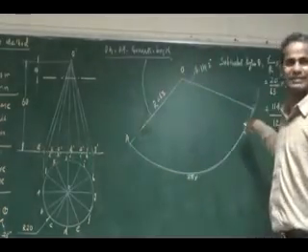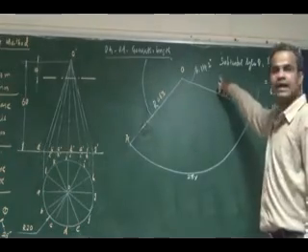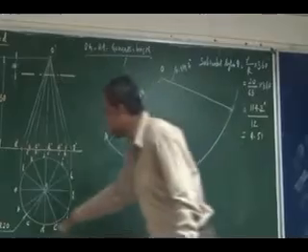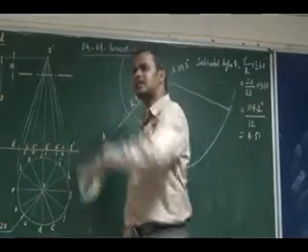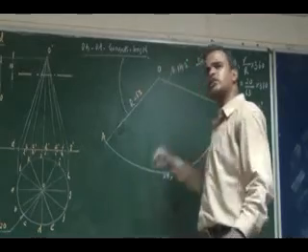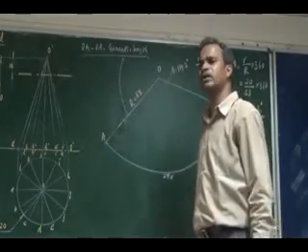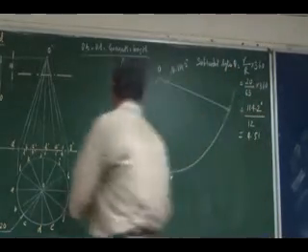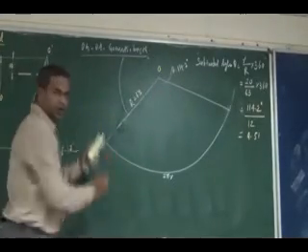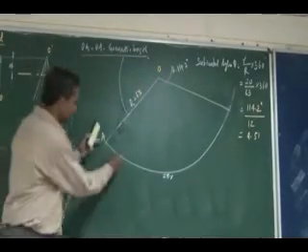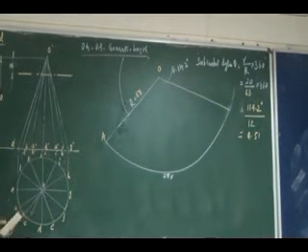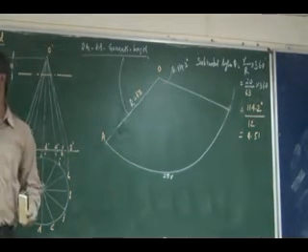So once you have drawn this development for this angle, either you can use this or the circumference length. The circumference length is 125.6. By dividing that by 12, I will get 10.4. So 10.4 you measure in your compass and cut along your R. Otherwise, measuring this segment of R is not correct. Exactly, it is not right.